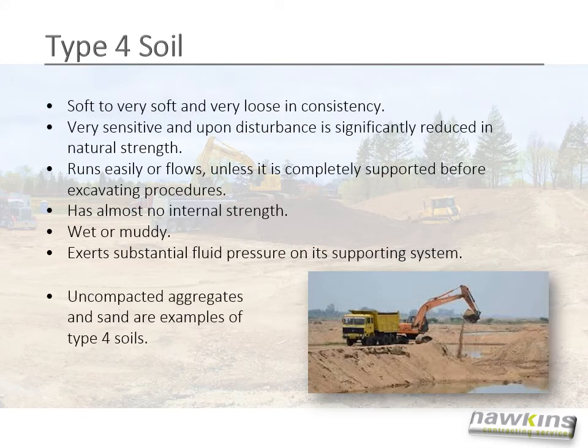Type 4 soils are soft to very soft and very loose in consistency. They are very sensitive, and upon disturbance, they're significantly reduced in natural strength. Type 4 soils run easily or flow unless completely supported before excavating procedures. It has almost no internal strength. It's usually wet or muddy, and it exerts substantial fluid pressure on its supporting system. Granulars and sands are examples of type 4 soils.